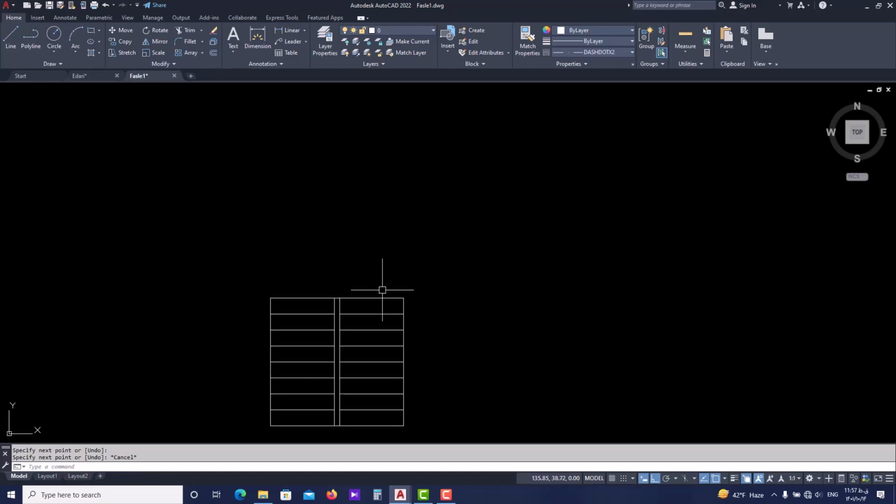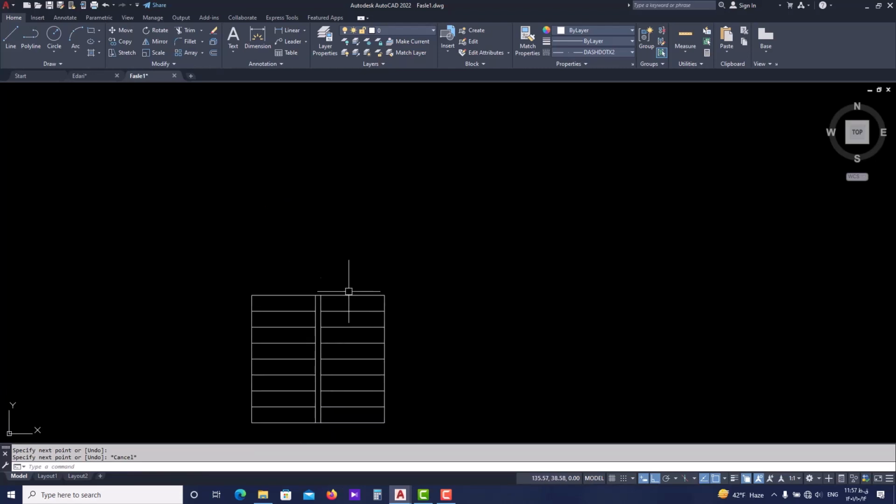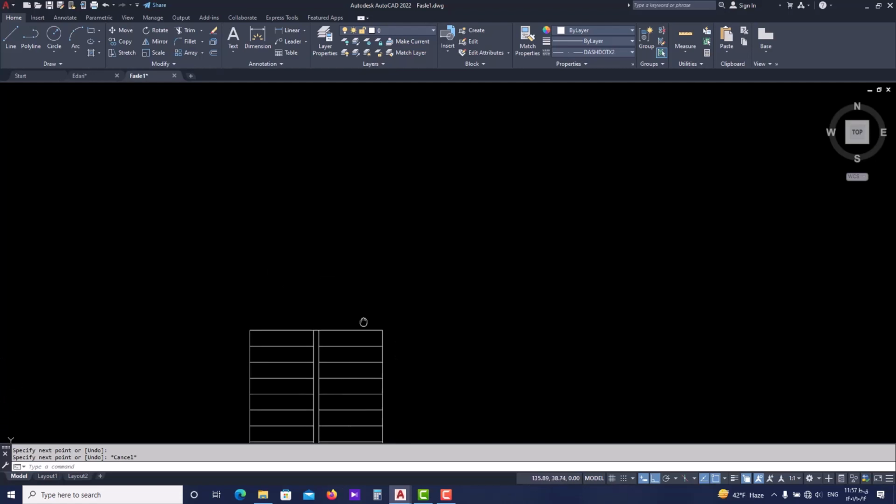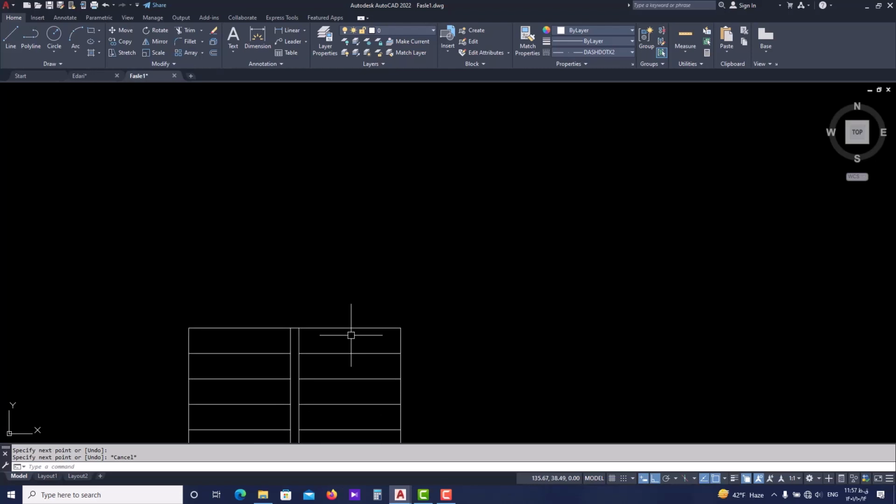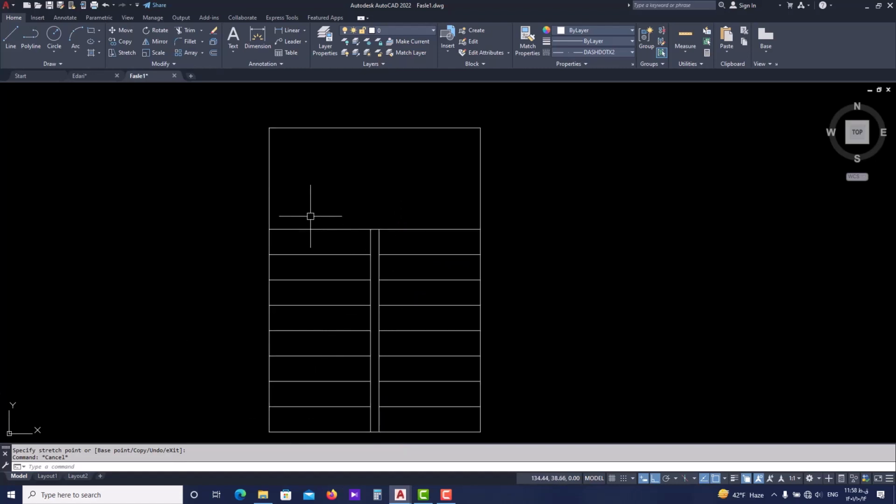And now let's work on the exterior walls around the stairs. But before that, let's talk about another point. Don't forget, we would have a landing up here, so we can again use offset to draw our landing. Again, the standard distance for the landing is 1.2 meters. And after that, we can easily draw the landing using the lines, because we haven't completely talked about fillet. Just like this, we can complete our landing for the stairs.